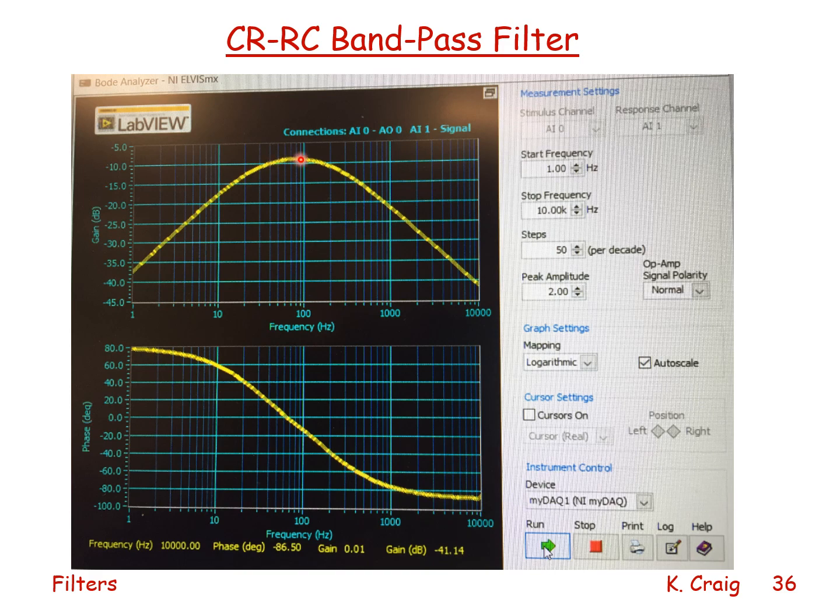And again, by my choice of R, C, and R for the high pass, R and C for the low pass, I will get different plots. But you can see it goes from essentially 90 degrees at low frequency to minus 90 degrees at high frequency and 0 degrees at maximum. The amplitude ratio is a maximum. So this is the experimentally determined bandpass frequency response plots.